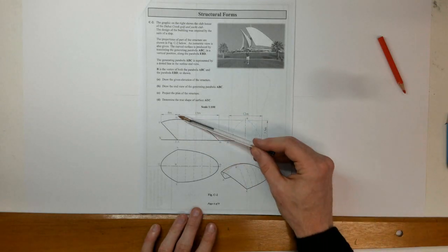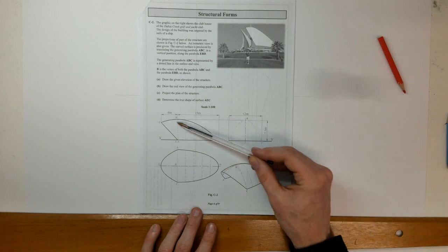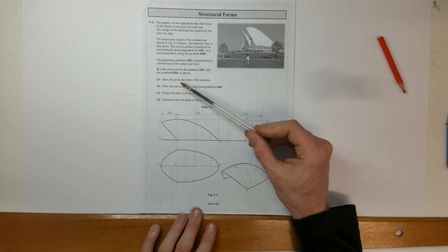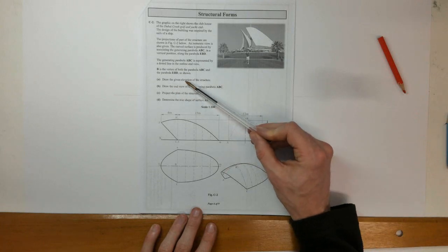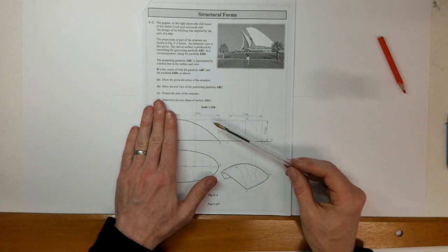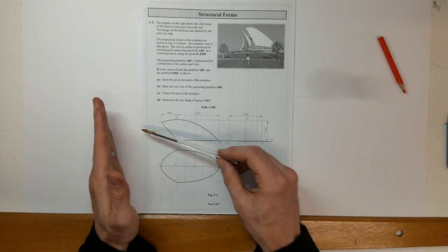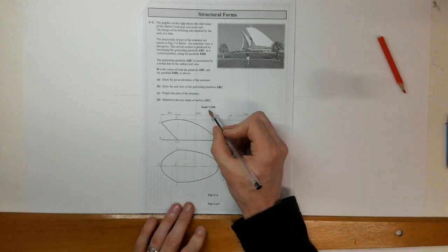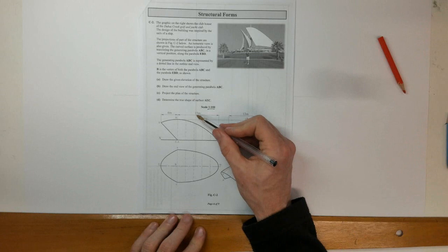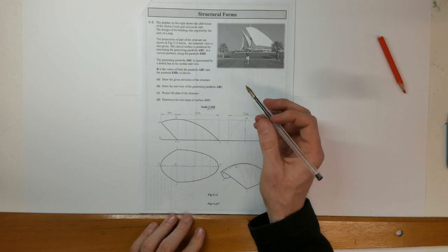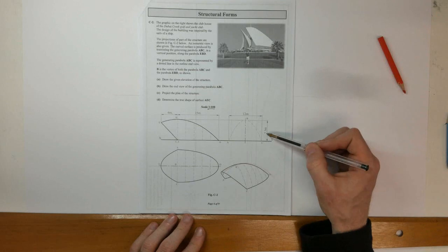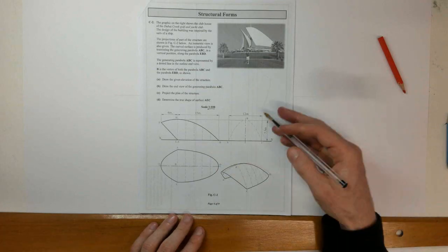We have the width, or half the width, of the rectangle it's going to fit into, and we have the height. So first off, they want us to draw the given elevation of the structure. As I said, that's a half parabola, and we can find the other side of it. Our scale is 1:100, so 15 meters is going to be 150 millimeters. That'll be 60, 120, 75, and so you can write in those measurements.